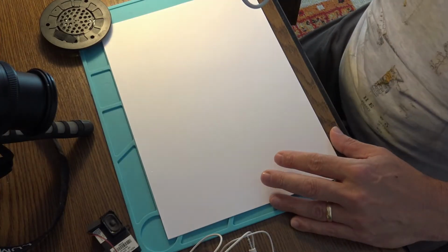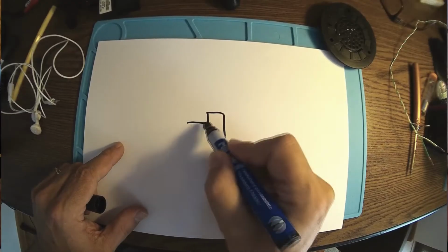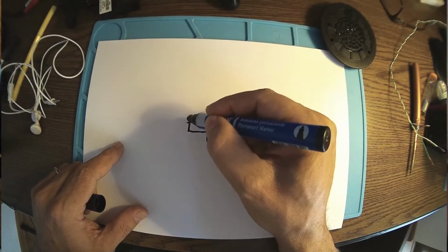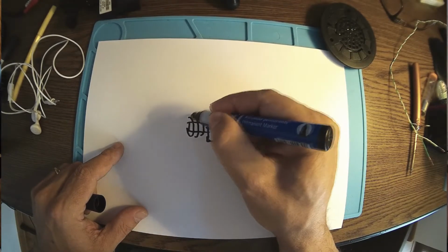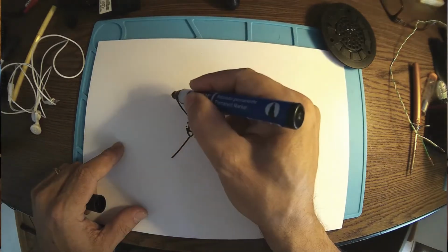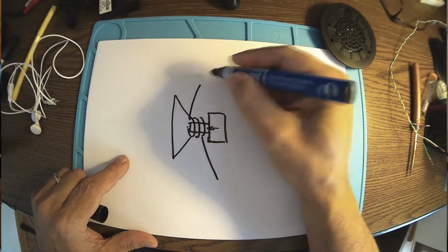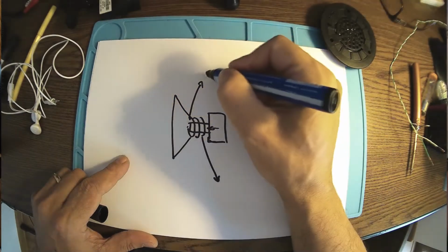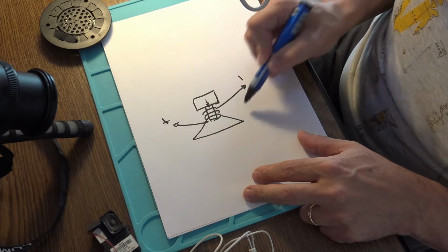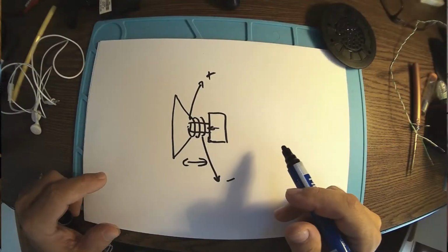What that means, let's say we have a magnet, and here we have a cylinder with, of course, magnetic properties, and around the cylinder we have a moving coil, and this coil is connected to a membrane. Let's say one end and the other end of the coil. When we apply a current of any kind, then the coil will go in and out, depending on the intensity of the current.